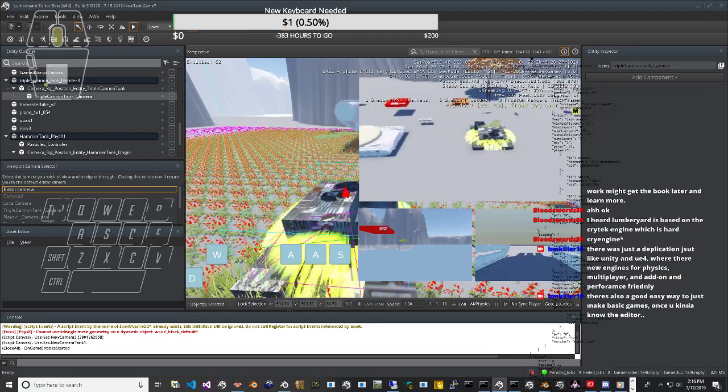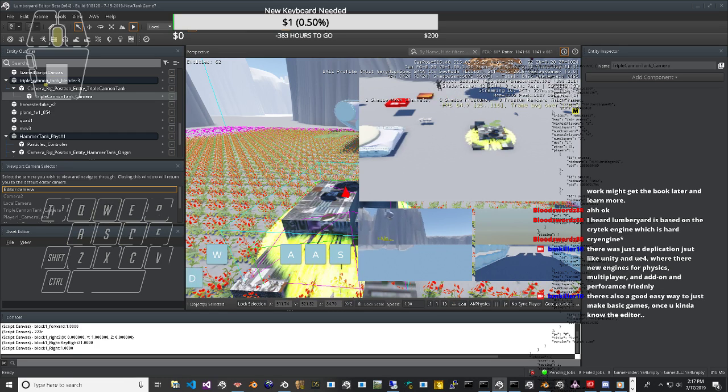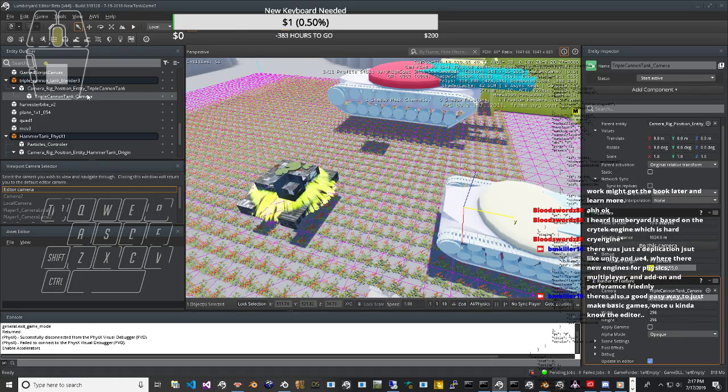These Bi numbers serve as coefficients in polynomial expressions over Fz. So, B5Fz is dimensionless, as must be the argument of the exponential function. B3Fz2 plus B4Fz has dimensions of newtons, as does the entire product. Therefore, B must be dimensionless.